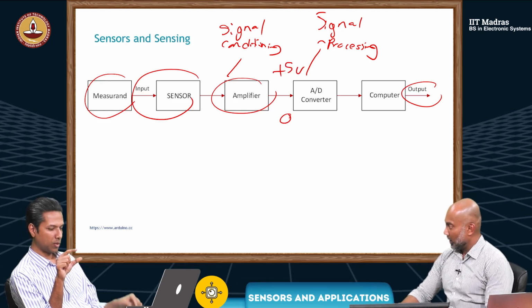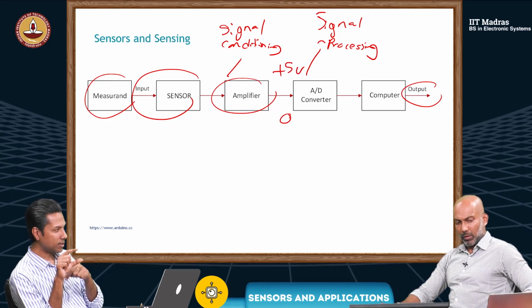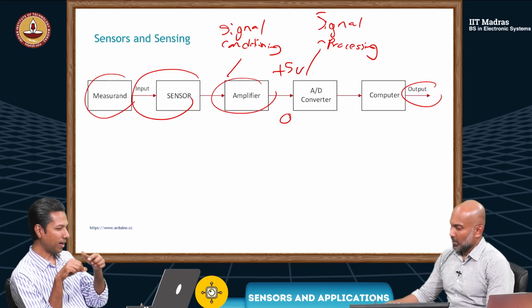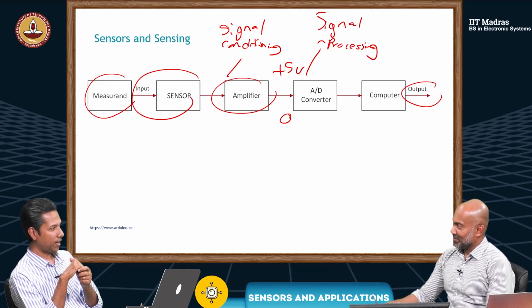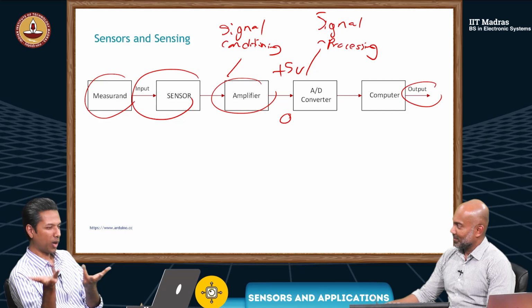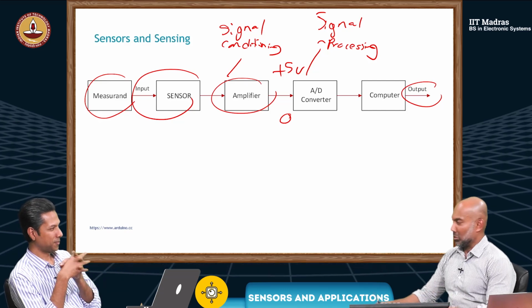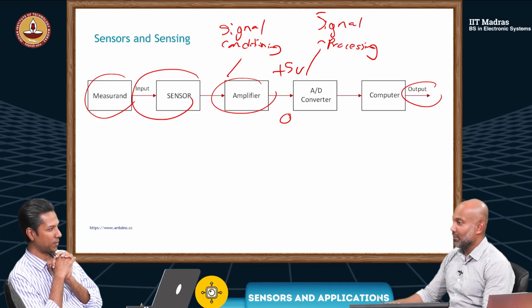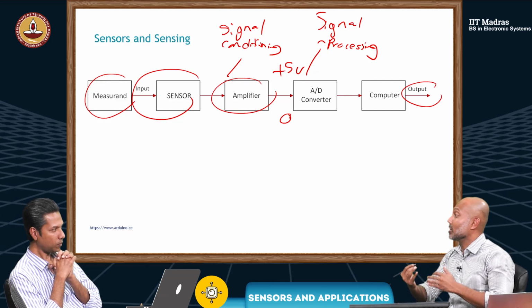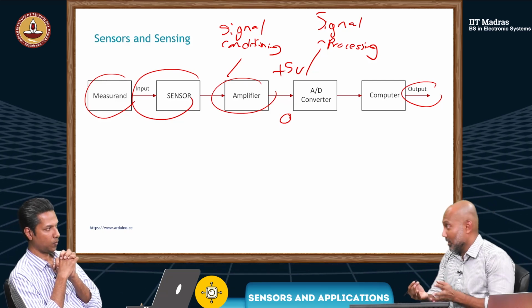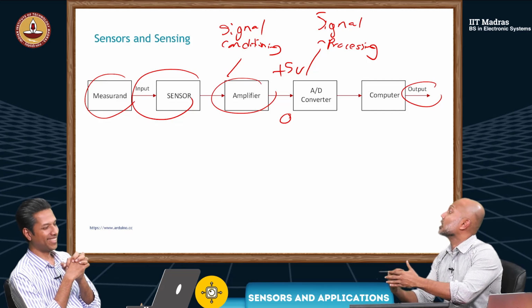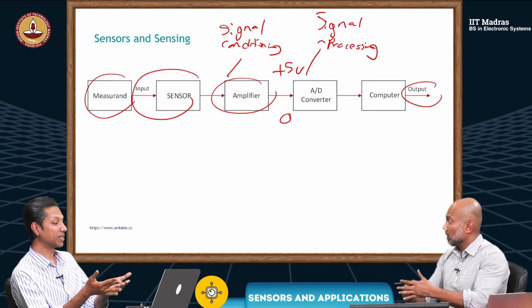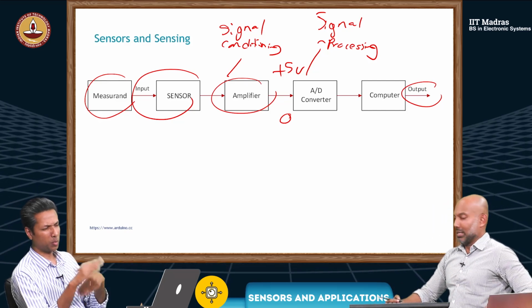Right? So if I give 1 millivolt to this ADC and then digitize, what I get maybe just noise. Right. And if there's a change in the temperature, you get the same signal again. You will not be able to distinguish. Yes. Unless I use a super ADC with so much resolution.